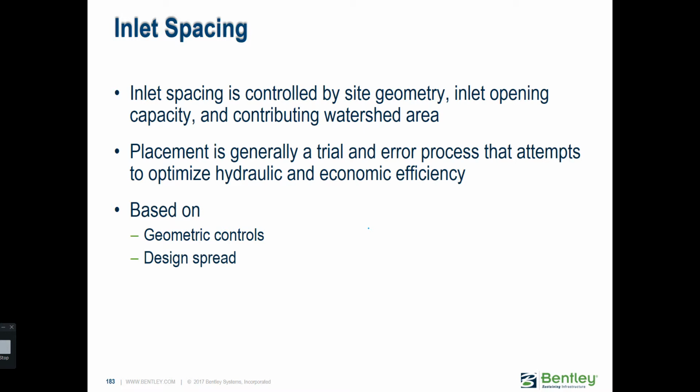So if you put really large inlets, you're not going to bypass that much flow, and therefore you don't need them as close to each other. And it also depends on what kind of watersheds we have. If we're talking about completely paved surfaces that are discharging directly to our road, then you're probably going to need more inlets than you would otherwise.